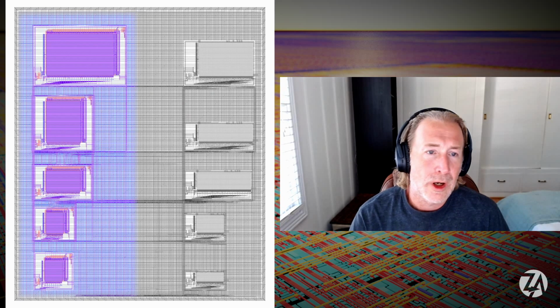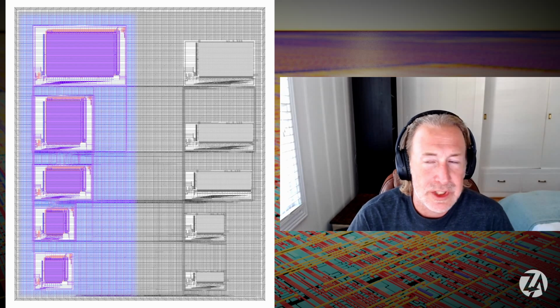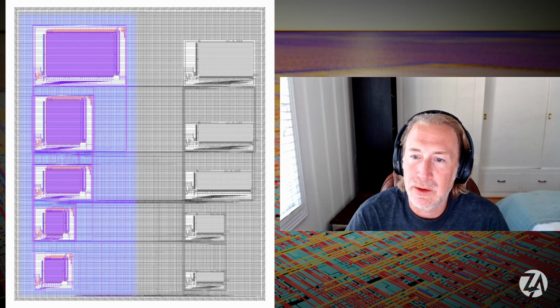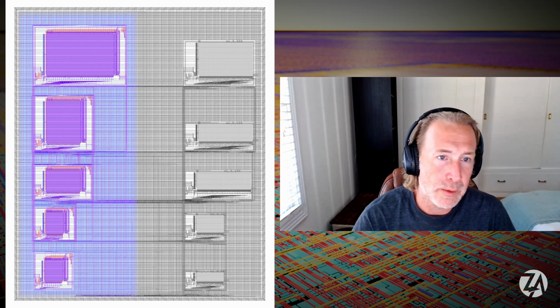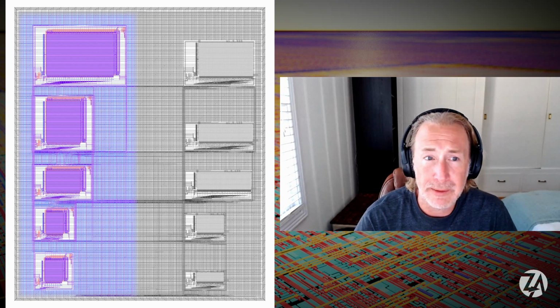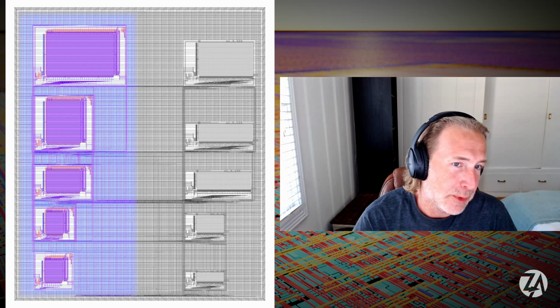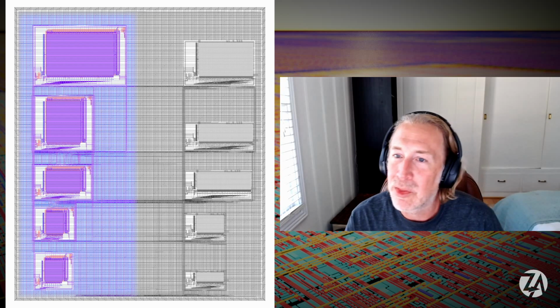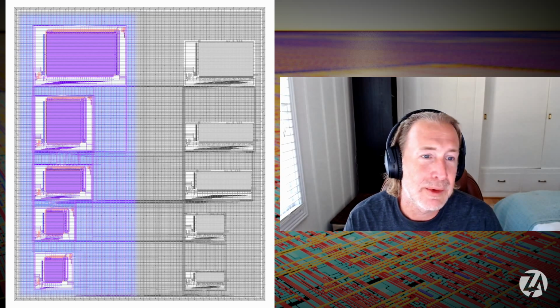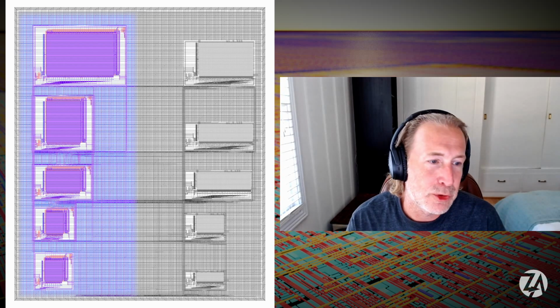Okay, so maybe you could talk us through the layout of your application for MPW2. Yeah. The goal of this one was to have more functionality of memories. In the pre-MPW tapeout and MPW1, we had focused on a dual port memory, with one read-write port and one read port, and all the five memories on the left of the image are dual port memories.